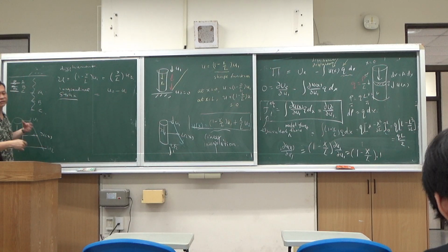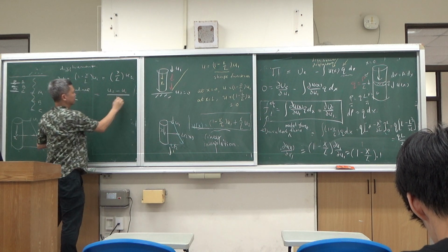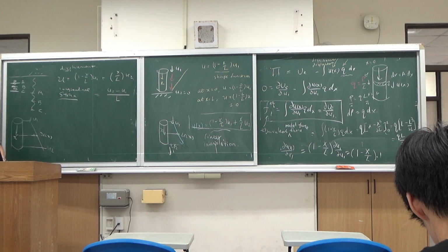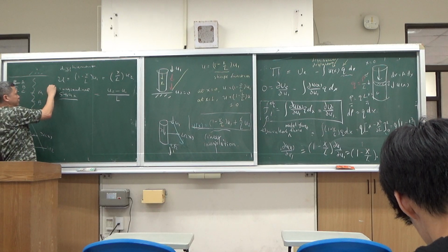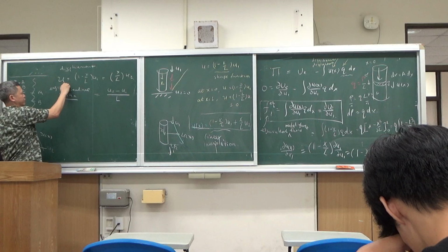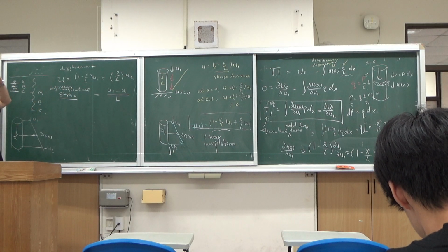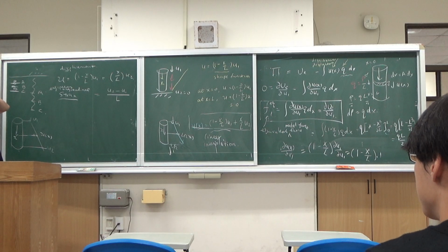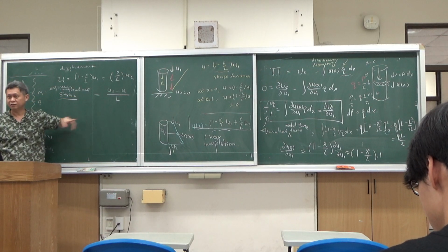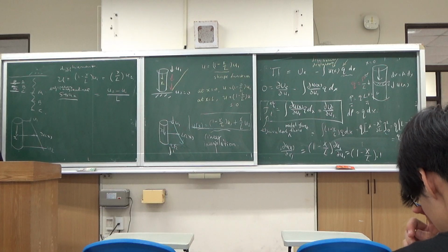If this is the difference, this is just an extension. You still have to divide by the original length. So this is what you define as your engineering longitudinal strain. The bottom displacement minus the top displacement is the total extension. So if it happens that bottom and top move the same, then you have zero strain, you have rigid translation.